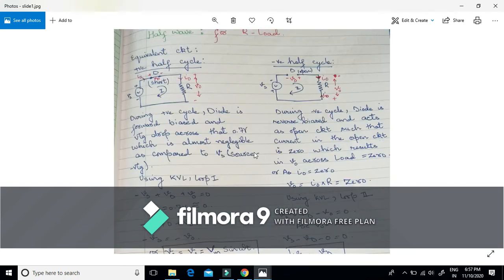Since we are applying sinusoidal voltage, we have a positive cycle and a negative cycle. Now we are analyzing the circuit for the positive half cycle and for the negative half cycle. From omega t is equal to 0 to pi, our source voltage is positive, or we can say across this diode, the anode terminal is positive with respect to cathode.